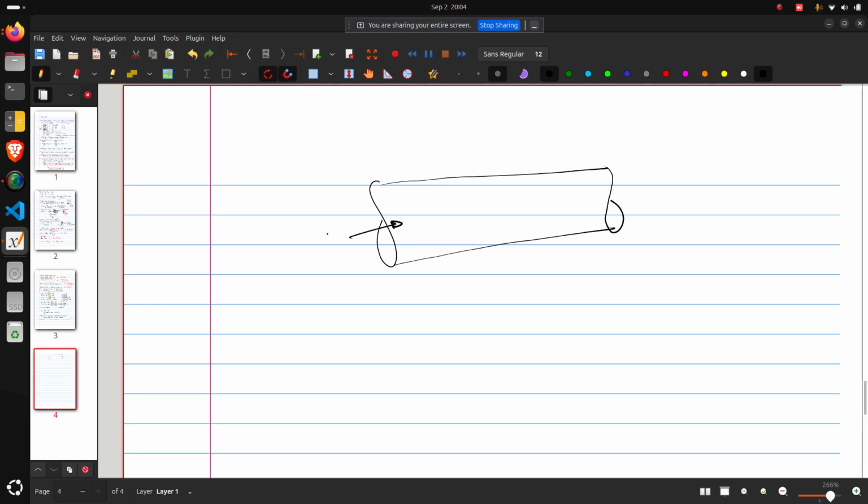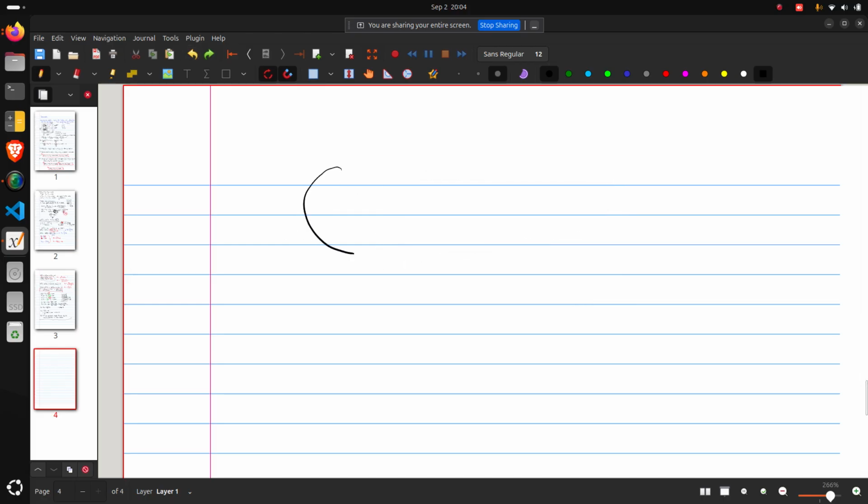If you look at the pipe from this side, what will you see? You will see a circular cross section, where there will be some velocity profile. If you have done a fluid dynamics course, then for a laminar flow it is something like a parabolic profile, right?